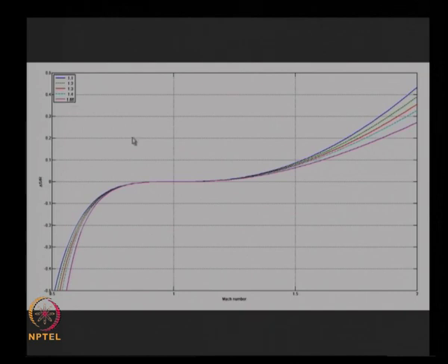So what I see is the blue line corresponds to gamma 1.1. Gamma can go only from 1.67 to 1, somewhere there. 1.67 is your noble gases or inert gases, monatomic species. So that is sitting something like this, it is on the bottom end here and it is also on the bottom end here, and what we are seeing predominantly is delta S by R equal to 0 when M equal to 1.